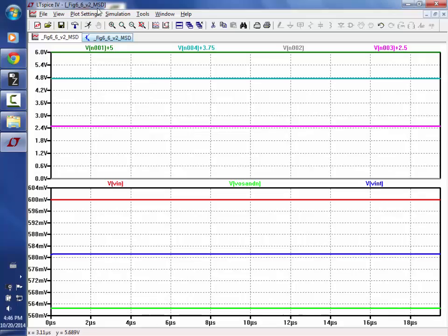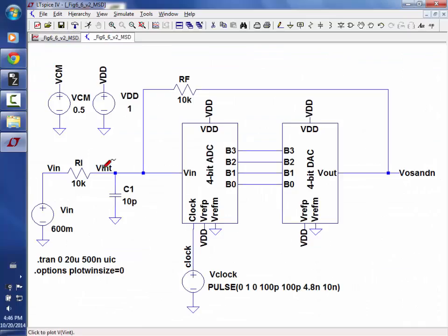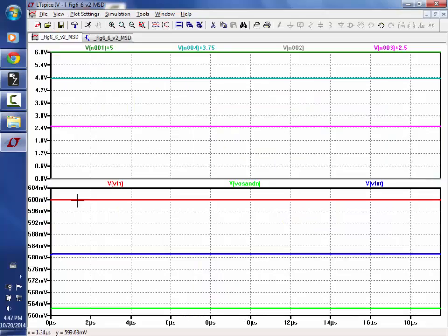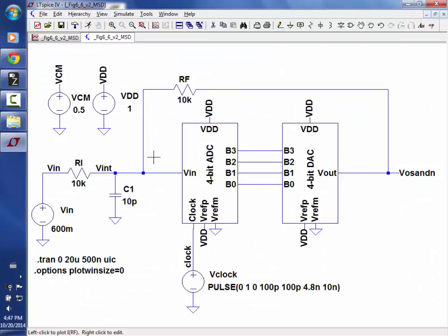Well, but the problem is if I look at this, there's no noise shaping here. It's just basically converting. And so maybe it's because there's a dead zone. Does everybody follow what we're looking at? So I look here, the input's at 600, the output is at 563, whatever, okay? If you do the difference, 600, 563, there's going to be some intermediate voltage there. It's going to sit there, right? And the output code is never going to change. So let me think about this for a moment.